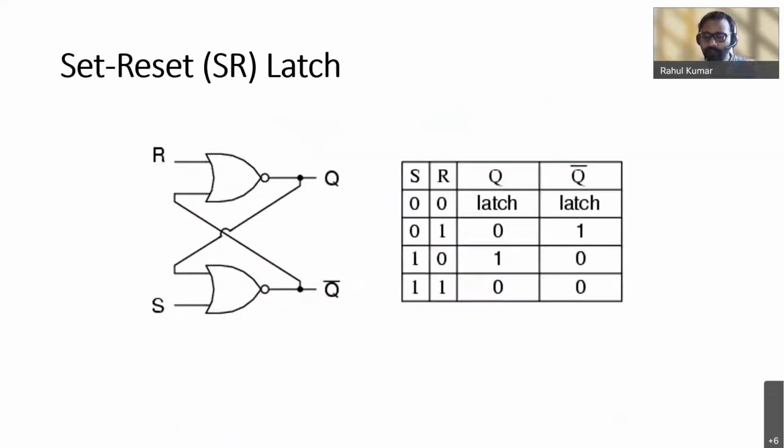Now there are several types of latches. Since latches are the building block of flip-flops, let's first try and understand latches, and then we will move forward and study flip-flops. So this latch over here is made out of two NOR gates.